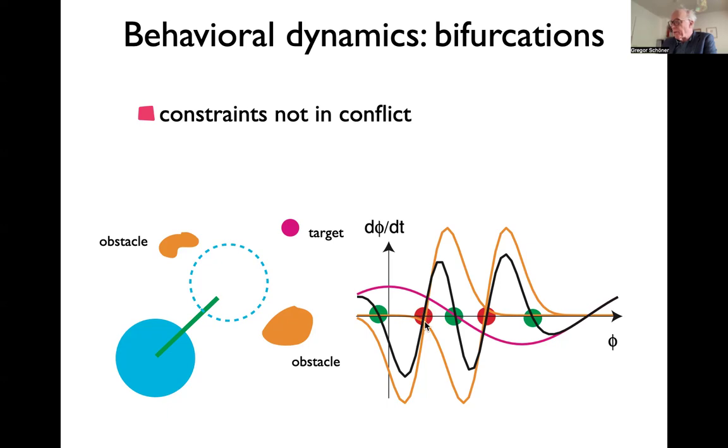So one erects a repeller here, the other one a repeller there, and the attractor in the middle comes from the target contribution in this color. The green are the attractors, and red are the repellers. And you see that the repellers are exactly where the individual contributions would want to put them, and the attractor is where the individual target contribution would put it. So inside here you have the same that you would have for each individual contribution.